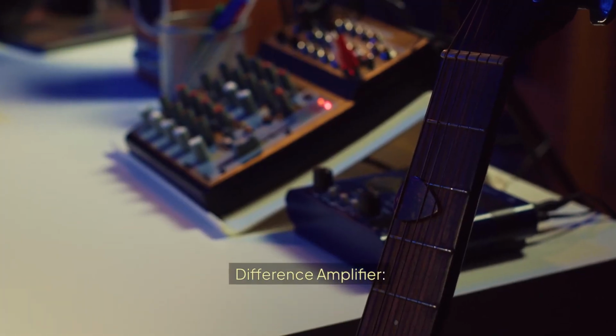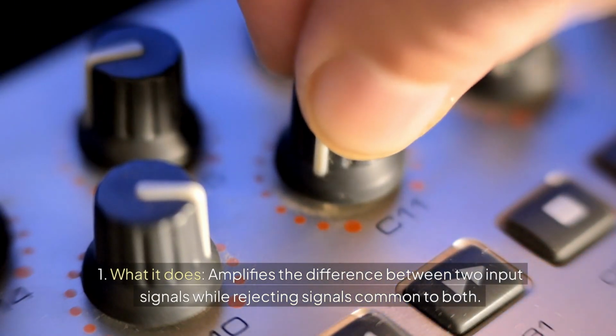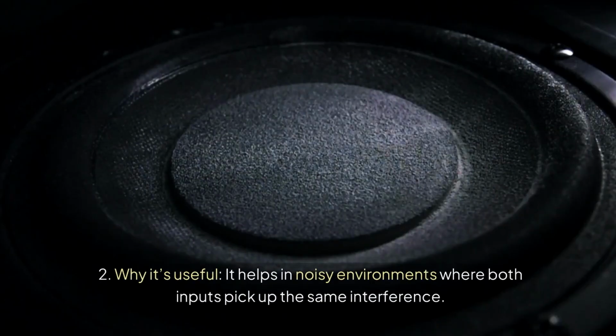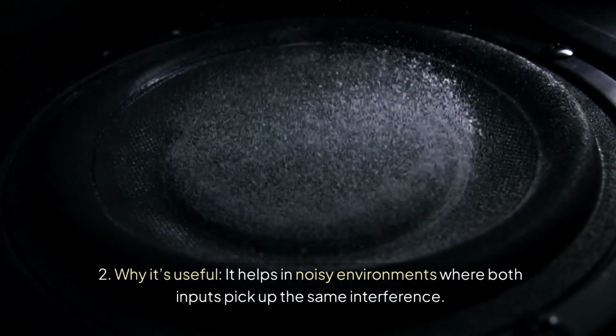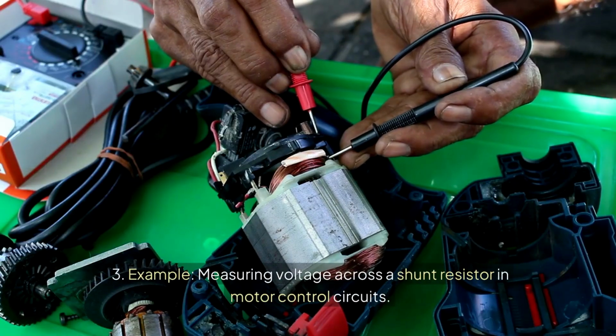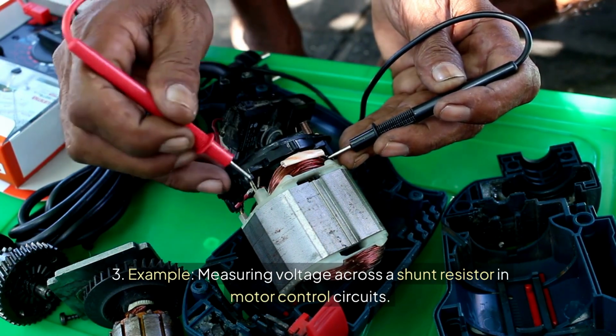Difference amplifier. 1. What it does: amplifies the difference between two input signals while rejecting signals common to both. 2. Why it's useful: it helps in noisy environments where both inputs pick up the same interference. 3. Example: measuring voltage across a shunt resistor in motor control circuits.